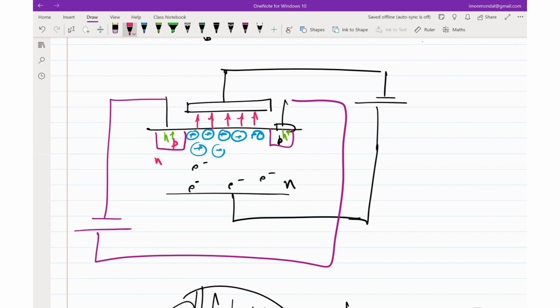So let's assume this PN junction is reverse biased. So if we do that, then under any circumstances, do you think an electron or a hole can flow in this direction? No, right? Reverse biased junction, nothing can flow in principle. There is still some leakage, but let's ignore the leakage for the time being. So no electrons can flow.